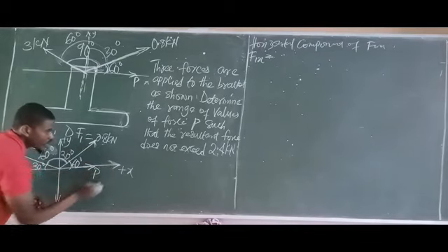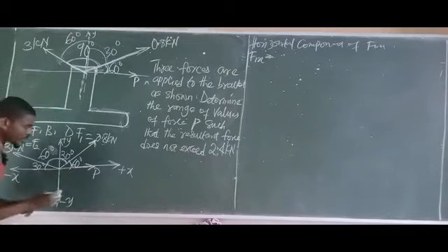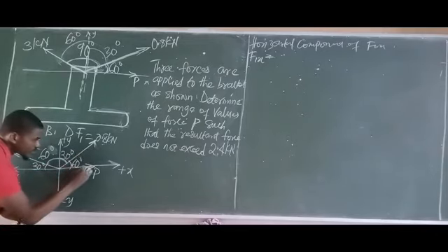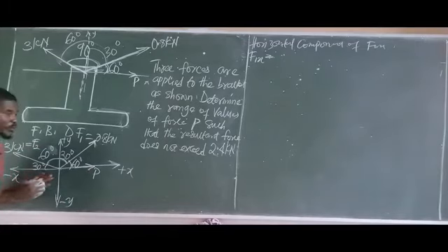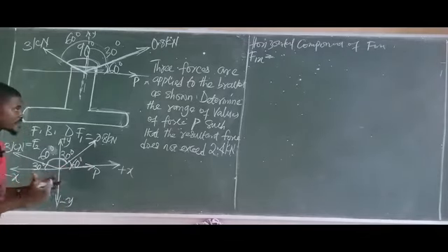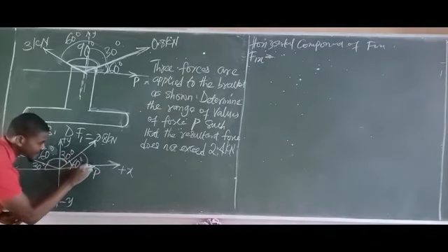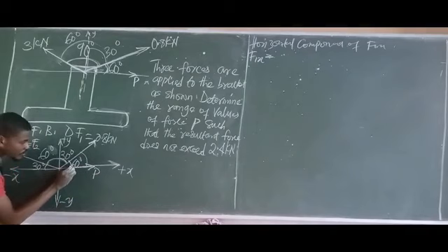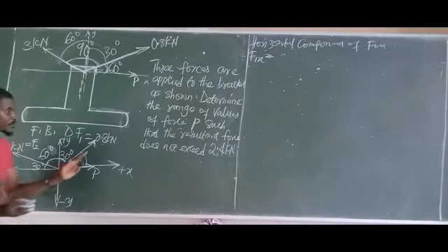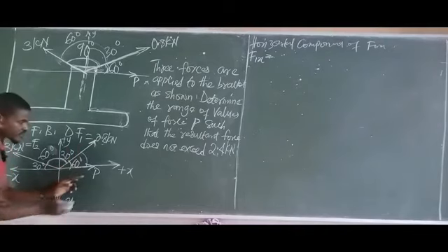If you pull this force to meet this line, observe the direction of the arrow of this force. It points to the right, so it is positive in the X direction. Then again, it passes through this angle. This is our shortcut and it works perfectly fine. It passes through this angle 60 degrees. So we said that you multiply the force by the cosine of the angle it passes through to resolve it to any direction you want. So if I'm resolving to X, which means it passed through this angle 60 degrees, I'm going to multiply 0.8 by cos 60, because it passes through 60 degrees.